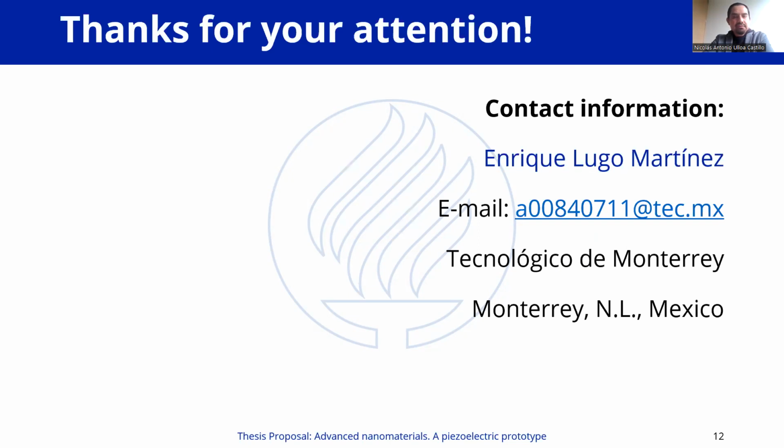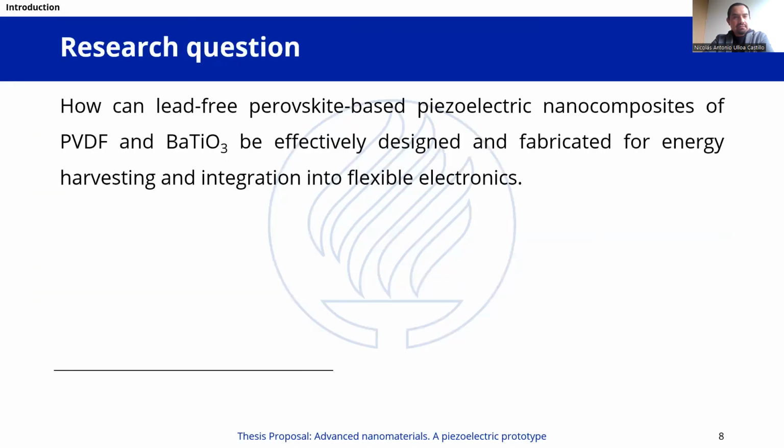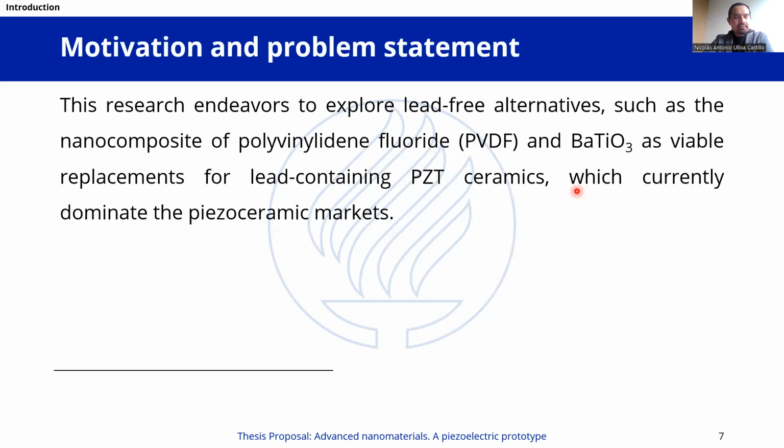Well, as I was talking, maybe I can go to a slide where I mentioned PVDF and barium titanate. As I was also telling, barium titanate and PZT are ceramics, which means that they are brittle. So it's not that easy to have them in day-to-day applications. For example, if we would like to develop a wearable, you cannot use plain barium titanate in this kind of application, because, as I mentioned, they are brittle.